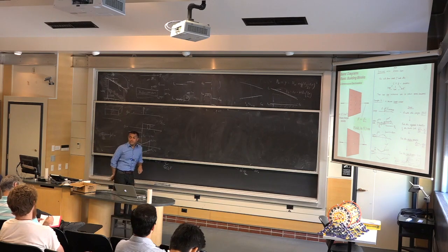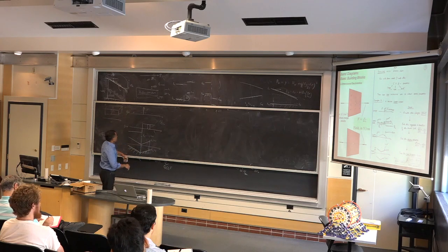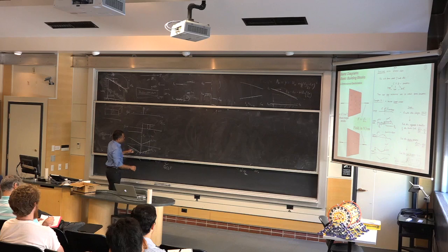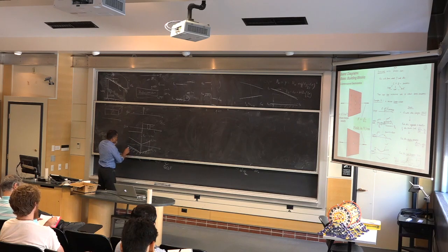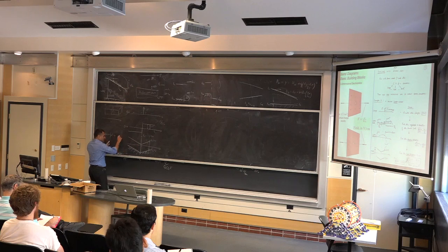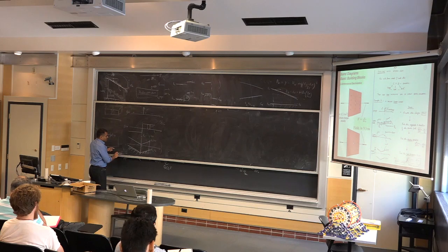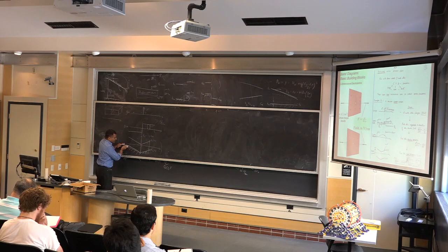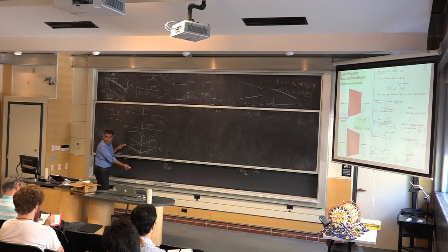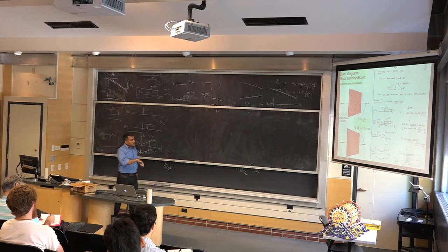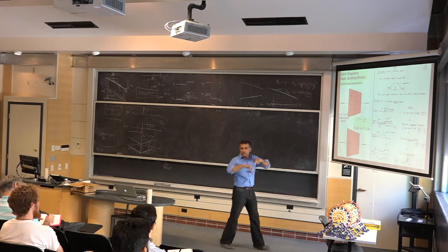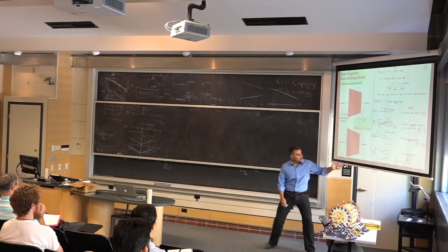So you can take that and then you can flip it around and say, well, instead of positive charge, I put negative charge. You can see everything will flip, and this will bend upwards now. If you have negative charge, it's going to trap holes. Right? So now, if you want to move electrons across this sort of a region, you see they'll get trapped. But holes, there'll be a big barrier for them. They will get reflected, because for holes, this is a barrier. Do you see that? This is a hole barrier. And so this is how you create a barrier. You can put a positive charge and create a barrier for holes and that sort of thing.